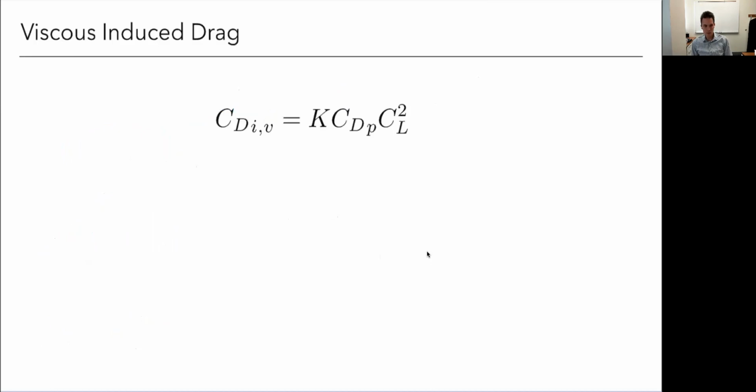One more thing we need to talk about to put this together. Remember that we said that this is all inviscid. This behavior is completely inviscid, right? If there was no viscosity, we still, to generate lift, have to have the air push us up. So we've got to push the air down, leave momentum behind, leave energy behind. That's drag, right? We left energy behind.